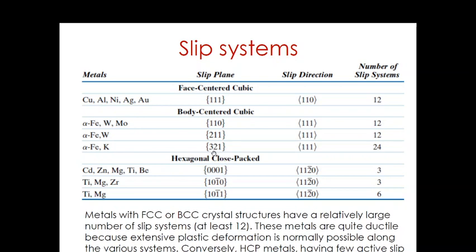For metals having these two crystal structures, some slip systems often operate only at elevated temperatures. Remember that only at elevated temperature will some of the slip systems operate, which means that metals having these two crystal structures have low ductility at room temperature.